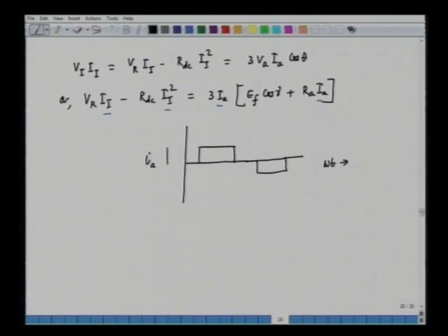Say, for example, we are talking about the phase A current, and the peak value of the current is II, the current of the DC link. The DC link current is reflected in the AC side, and the current in the AC side is not a sinusoid, it is basically a quasi square wave when the inverter is a current source inverter.